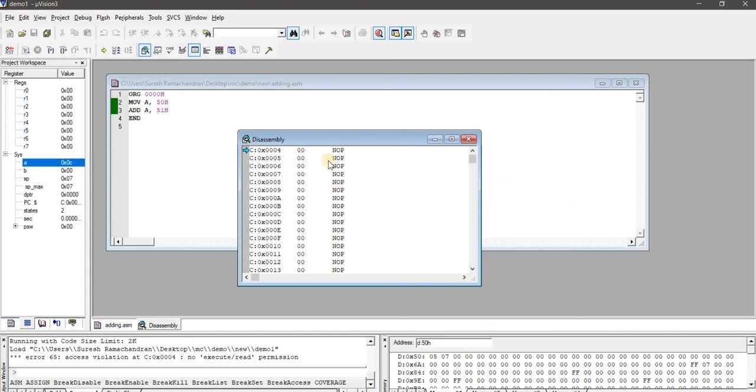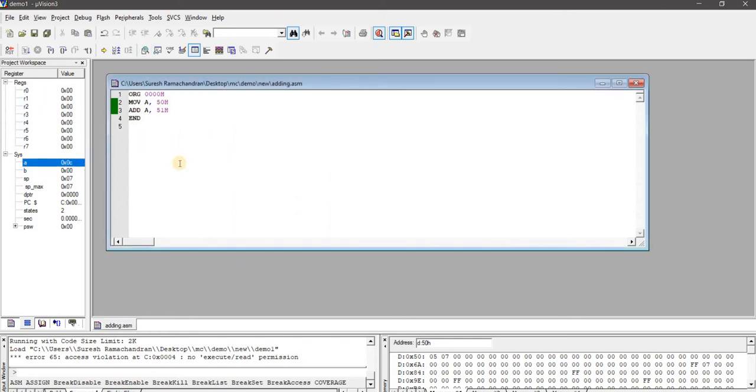That is a decimal number, but this microcontroller will always convert the decimal number into hexadecimal numbers. You can see the equivalent of the decimal number 12 is given as 0C. Okay, so this is how you can use the Keil Microvision-3 software package to run simple programs.